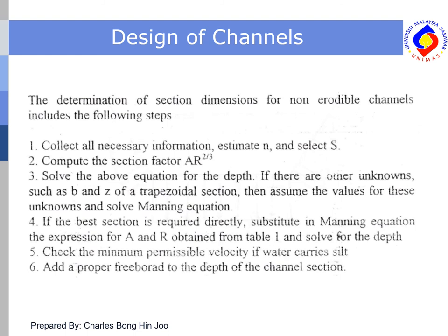So, from the previous considerations that we have seen in the previous slides, we can summarize that to design an open channel, we follow these steps. The first one is to collect all necessary information, and from this information it will help you to estimate the roughness and also the slope. This information may include the material of the channel and also the topography of the location where the channel will be designed, so as to determine the suitable slope.